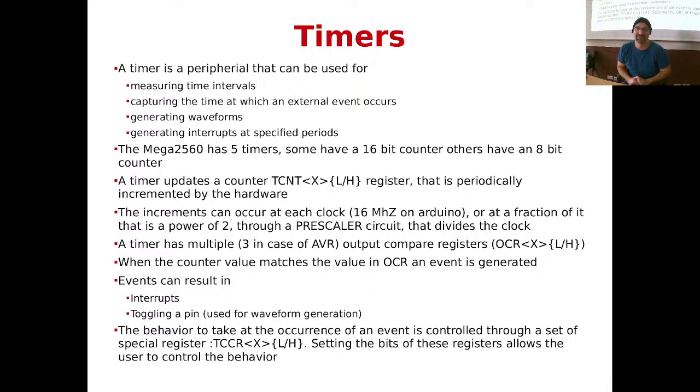Even a counter at 16 bits, I don't know, divide the 16 million by 16 bits, right? Roughly said, 16 million is 2 to the 24, 2 to the 8, 1 divided by 256, should be something like that, no? So which will be a frequency period which is higher than 100 hertz. We are in the range of 100 hertz with a 16-bit timer. So what normally you have,